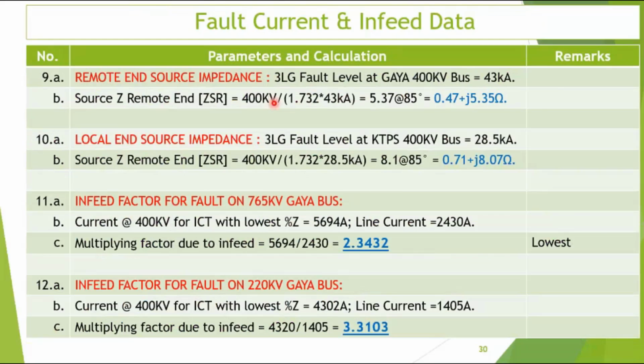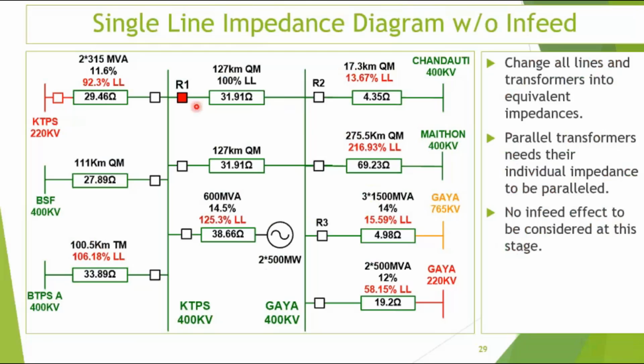Again, go back to the diagram, because without the diagram we cannot understand. Zone 4 of this relay should not encroach beyond zone 1 of this relay. This is the reverse shortest line. If such a thing happens, suppose this relay's zone 2 is 500 milliseconds and this relay's zone 4 is 500 milliseconds, and this relay encroaches beyond zone 1 of this line.